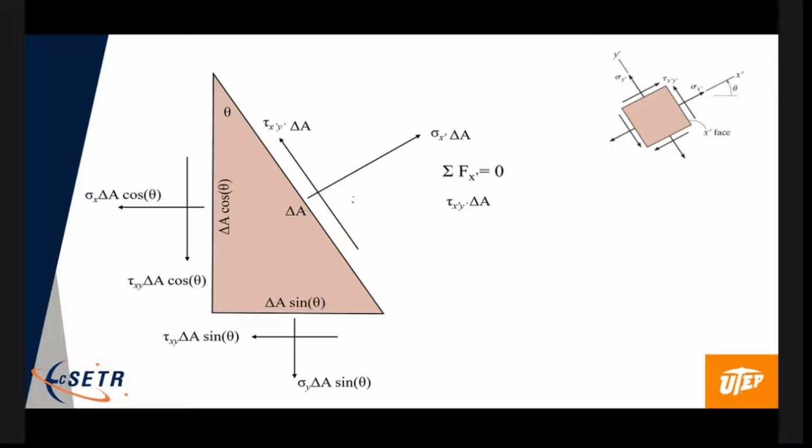Well, you know what? I think this should be a y prime direction. Let me just make sure. Yeah, this is a typo. This should be a y prime. So if we do sum of forces in the y prime direction, this way, that's what that is, right? And this is x prime.